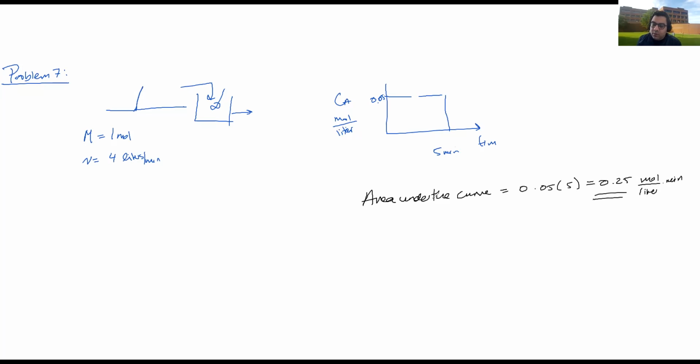Okay, so this is the area under the curve, and this number should match a similar number I get from here. Since you can't really get an absolute mass balance in terms of just moles or meter cubed or whatever, we need to compare these parameters. First one is the area under the curve. This is the approach to deal with these problems. Area under the curve here, and here I'm going to get the area of this tracer, or the area of this impulse signal.